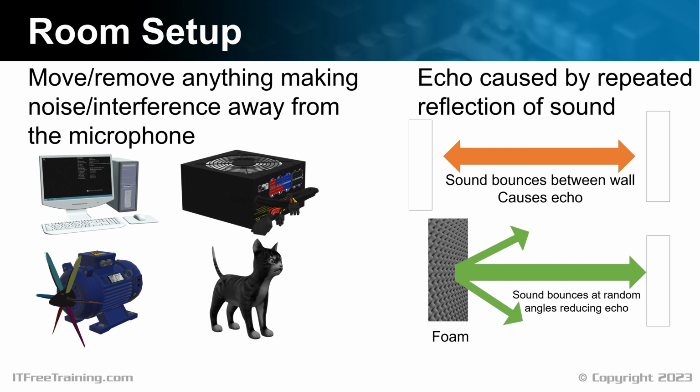In some cases, this may not be possible, for example, because of the costs involved, or perhaps you can't make changes to the room. Essentially, you only need to prevent the sound bouncing at right angles, so even something as simple as using a bookshelf will help, as long as the object is not flat, so all the sound waves aren't bouncing back in the same direction.